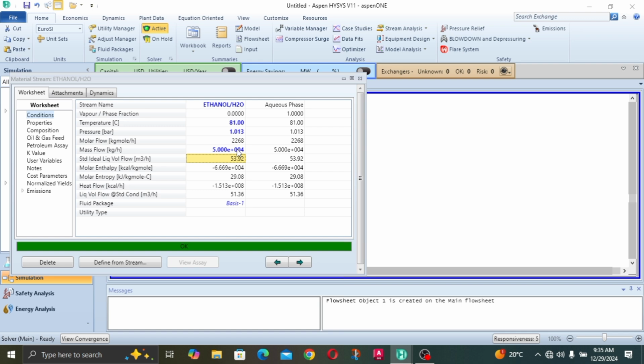With a simple distillation, we cannot achieve 100% separation between the two components, ethanol and water. We cannot separate them 100%, but we can hit a purity of 90% and above, hopefully. That's a good benchmark to hit. Then we will do a little bit of optimization, which might be painstaking and time-consuming, but it's for the best. We can see what the best purity percentage we can attain for the separation is. With that, we can go on.